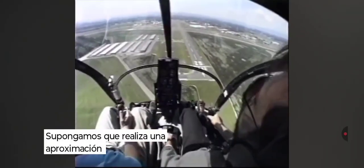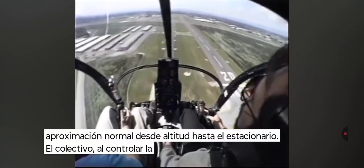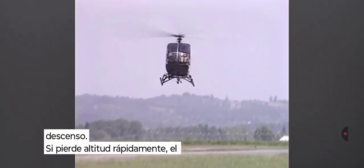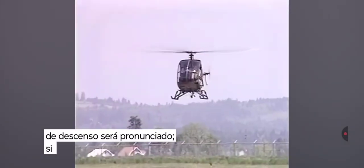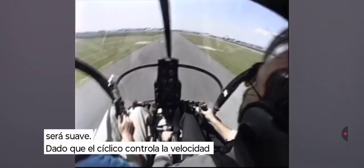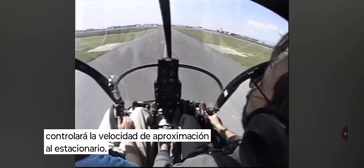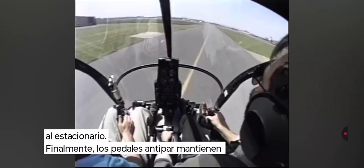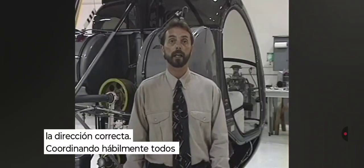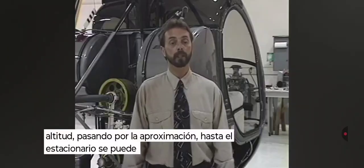Suppose you were performing a normal approach from altitude to a hover. The collective, because it controls altitude, will control the angle of descent. If you lose altitude quickly, the angle of descent will be steep. If you lose altitude slowly, the angle of descent will be shallow. Since the cyclic controls airspeed, it'll control the rate of closure, or how quickly you approach to a hover. Finally, the anti-torque pedals maintain heading and keep your nose pointed in the right direction. By skillfully coordinating all the controls, the transition from flight at altitude through the approach and into a hover can be managed smoothly.